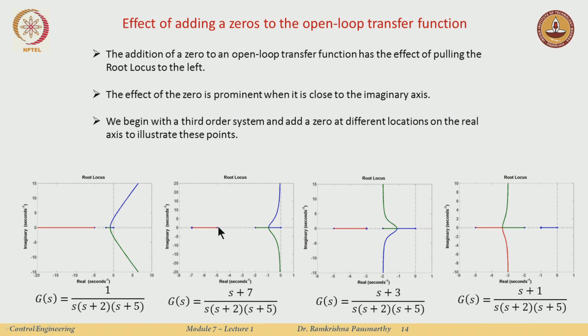So, well, this guy again will just move to the right and stop here, and now I see that the root locus has improved much, because if I were to deal with this gain here, you see that I am close to the verge of instability, right, this and this. So, this kind of adding a 0 makes my system stable because it is pulling this blue and the red lines to the left, but it may not be too good in terms of relative stability.